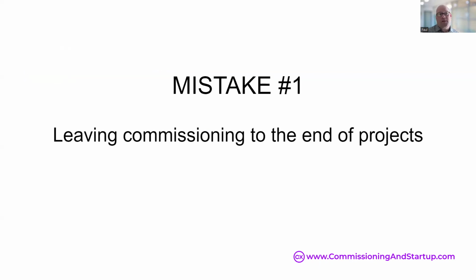They start to think about commissioning maybe only a few months before on-site testing starts, but this is what leads to problems on projects. In fact, to be successful, your commissioning processes need to start early in your projects during your FEED processes once equipment tag lists are available from design groups. Your project WBS rarely aligns with your commissioning and startup sequence, and you need to realign your project with a systems-based approach earlier in your projects before the damage is done and can't be repaired. If you don't get this right earlier in your projects, then it's pretty tough to fix later.